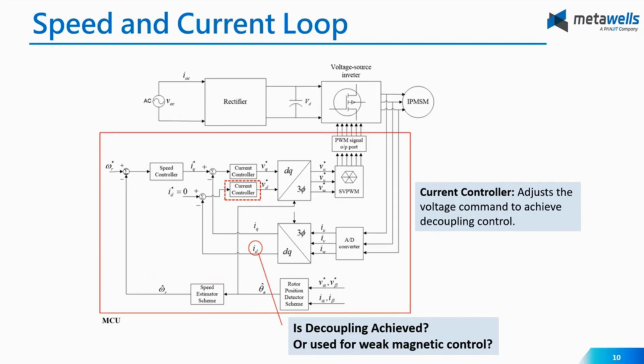Okay, let's talk about the current loop, second part. IQ control basis. The ID axis current in the DQ frame affects magnetic flux, and they usually control it to zero for max torque, but it can be controlled for specific needs. Here, ID is usually controlled to zero.